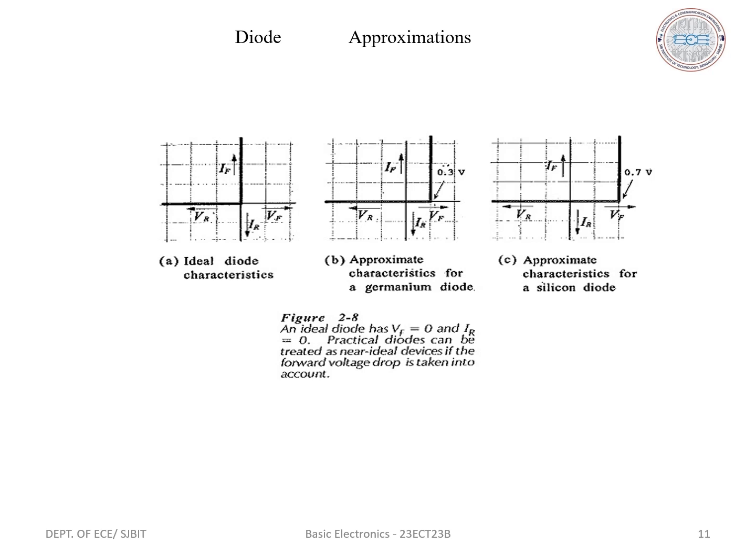Next, the second one is the practical diode equivalent circuit. This equivalent circuit consists of a voltage source and a negligible forward resistance. This equivalent circuit has the second approximation characteristics. Next, we have the third approximation, or piecewise linear, or complete DC circuit. The equivalent circuit consists of the diode dynamic resistance in series with the voltage source, and an ideal diode is included to show that the current flows only in one direction.